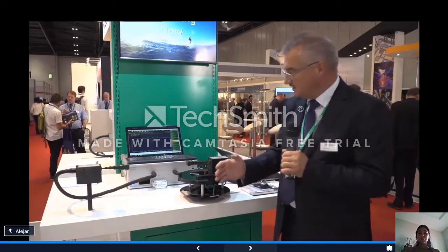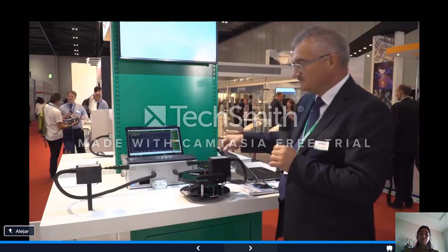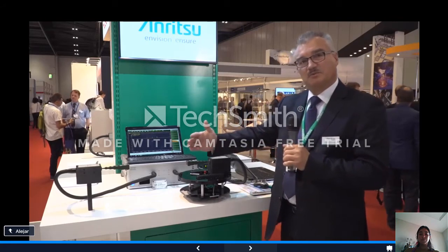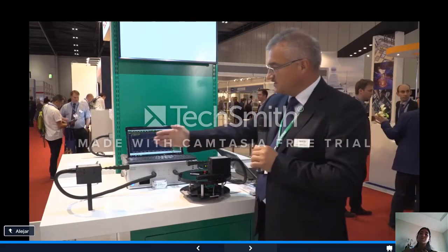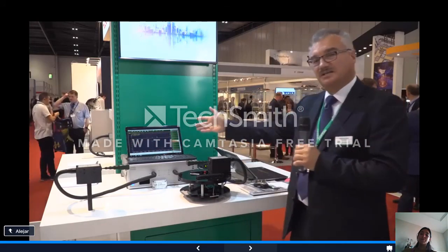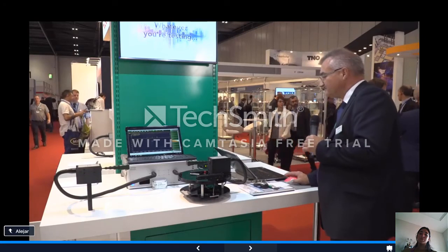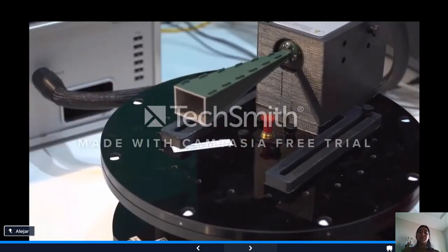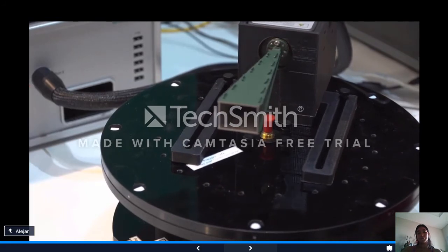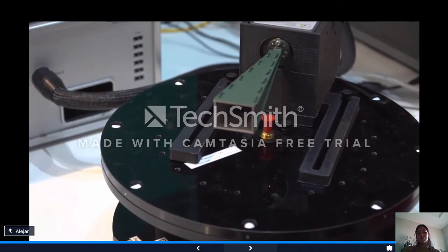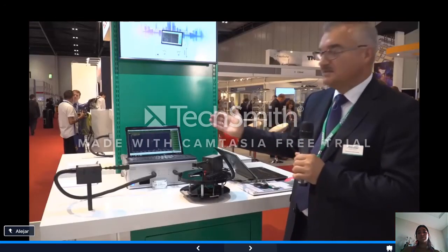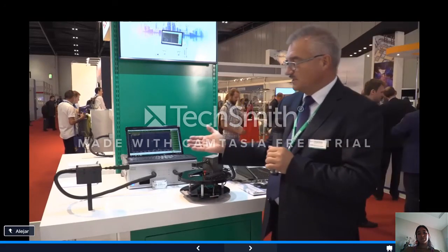What is missing is a rotating table, and on this rotating table is the antenna under test. This antenna starts rotating and sending a signal, and then we can see the antenna radiation pattern. First of all, the antenna is moving into a start position, and then it is moving back in equidistant azimuth points until the antenna has arrived at the other end. And this is just a proof of concept.